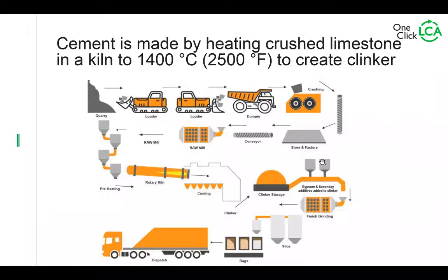And this is the source of our climate problem, really, or the biggest source of our climate problem. It's because the chemical bond cannot be broken at a low temperature. So we need to either have an alternative way of making cementitious material, or we need to find a way to make zero carbon temperature and capture the carbon arising out of the cement kiln. And neither of them is easy, right? That's why we have the problem.